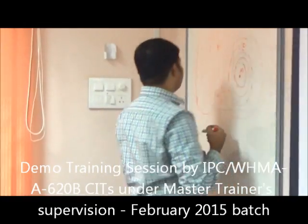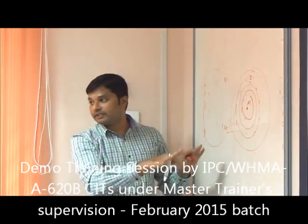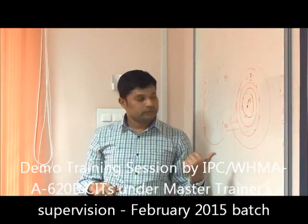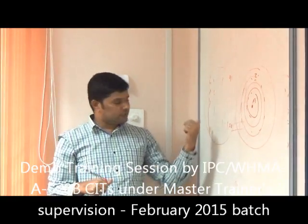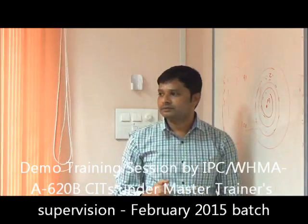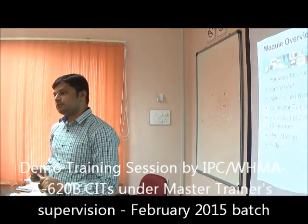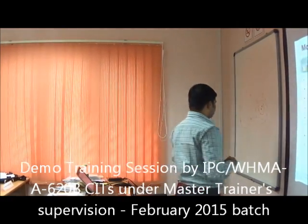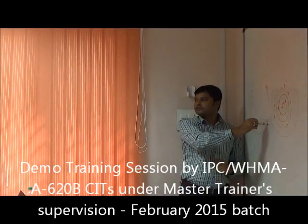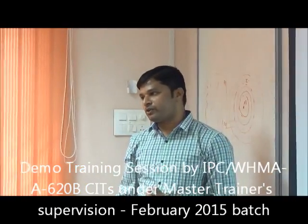So what will happen if you insert from the top? This is a standard method. It is defined as standard that if the first pin is in the center, we need to follow the clockwise. If it is leftmost to rightmost, then we follow from bottom to top. If I insert the contacts from the top, what will happen? Why should we not use it? When the topmost gets populated, it is difficult to insert the wire from the top. As you rightly said, if I insert here, the wire will be hanging like this. So it will not be feasible, or else it will become difficult to insert the next contact.